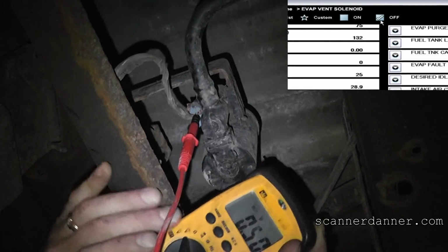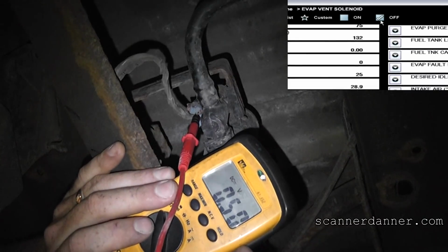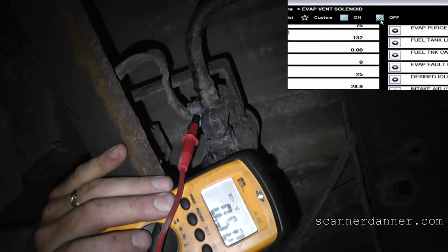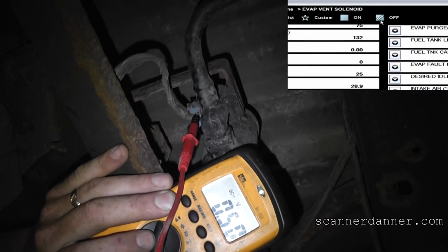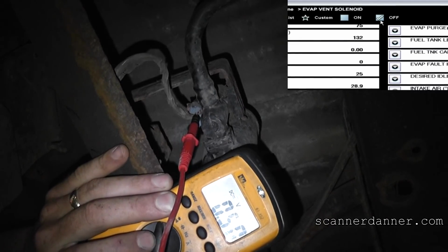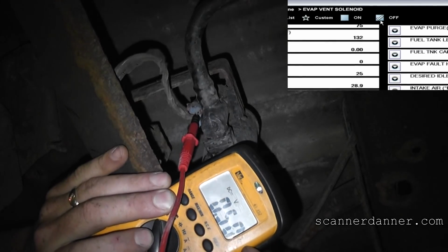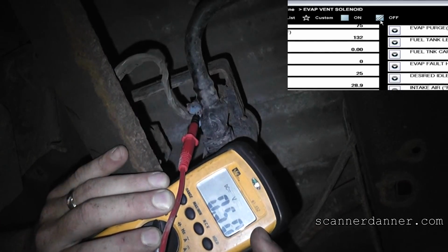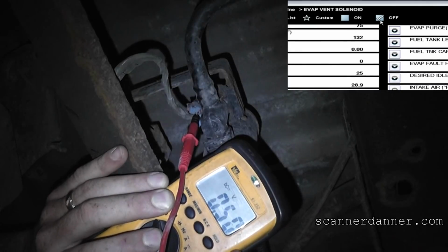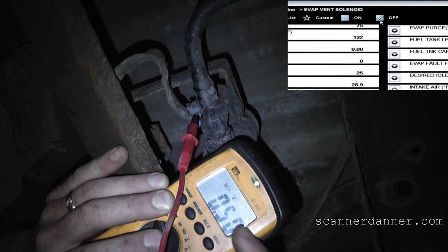This voltage is very, very low. It's basically an open circuit. There is a trickle coming through. There's such high resistance in this solenoid that we're pretty much open. There's just a trace of voltage coming through. If this meter didn't support some type of current flow, I know it's a 10 megaohm impedance meter, but there is still some trace through this. This would actually potentially still be 12.